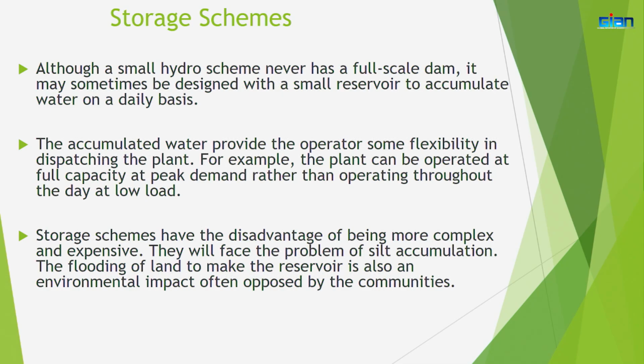So, the storage schemes are more complex and expensive because of the reservoir, and they will face the problem of silt accumulation. In large reservoirs, over the long term, silt will accumulate in the reservoir, and the reservoir's water capacity will gradually go down.